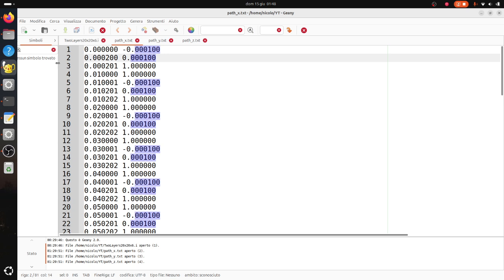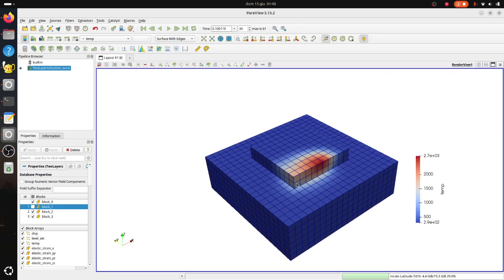My element size, as you can see, so this is 200 micron, so one of these elements will be about 20 micron, and each time step the source is moving a bit more than 0.1, so hundreds of time steps for the source to scan one element. It may be a bit too conservative, but I found that in this way I can ensure good convergence and there are no time steps that get cut.